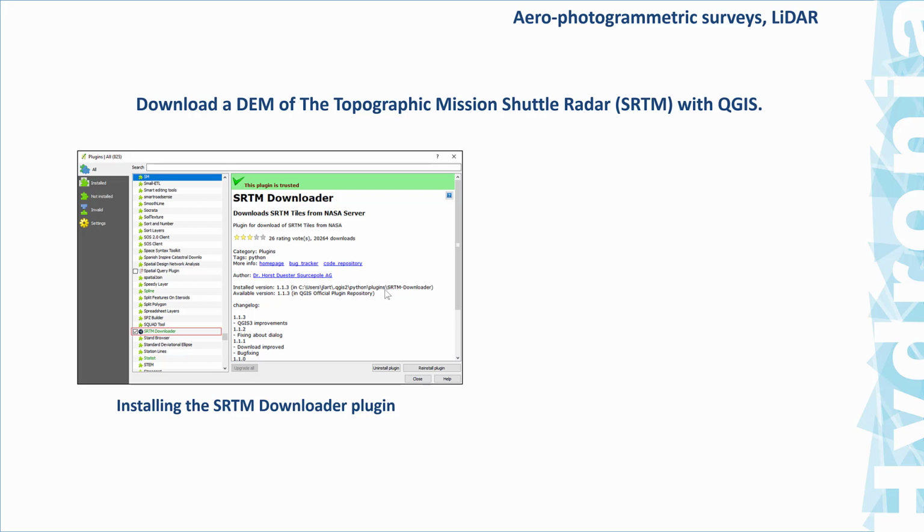If you want to use directly the data format that is provided in this, you can download a plugin. And this window that you see here, that we will be coming back to, is a window of the QGIS software that you should have installed in your computers. If you manage the plugins, you will see that you can have a large number of free plugins that you can download. And one of them is the SRTM downloader that downloads data directly to your area of interest, and you can use that to obtain the data in the format that you require.